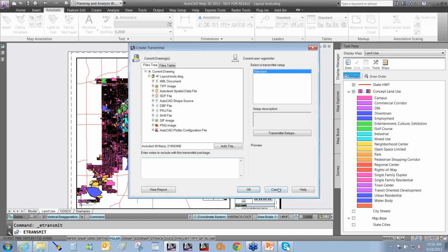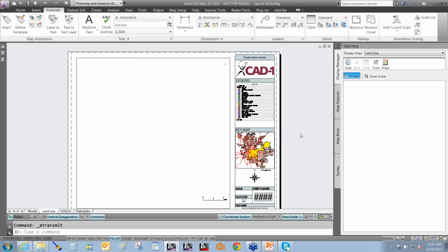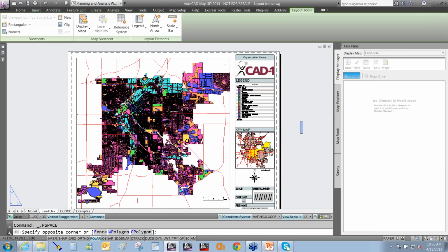If you are attached to an Esri database, you're going to want to take extra steps. For example, I can export my map to a particular drawing, or I can use other tools to import that FDO information and lock it down as AutoCAD objects. But you'll need to take an extra couple of steps. If it's just files that you're downloading, those will go with it. The other thing to remember is that the files will go with you into the e-transmit, but the person on the other end had better be using Map or Civil 3D. Otherwise, they won't be able to see a darn thing.